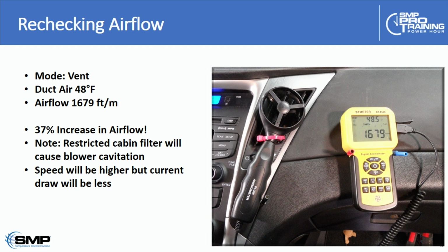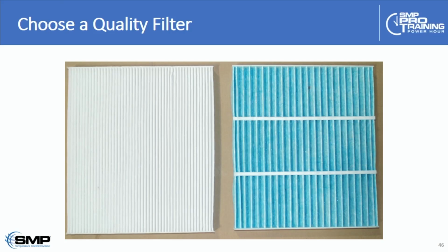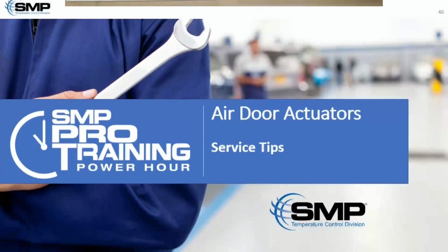The point I'm making here is that I have seen replacement filters that can be quite expensive, and the material and design of the filter is important. The filter on the right here was the one restricting the airflow. That filter was causing a significant restriction in the airflow, and that's what was causing the customer to still be unhappy with the airflow even after the filter had been replaced.